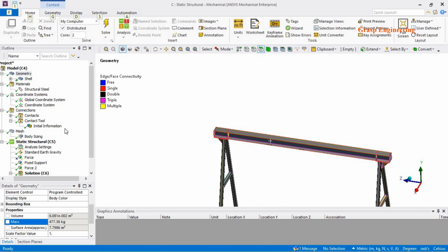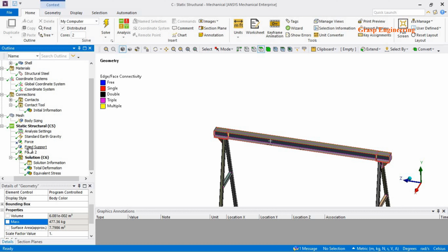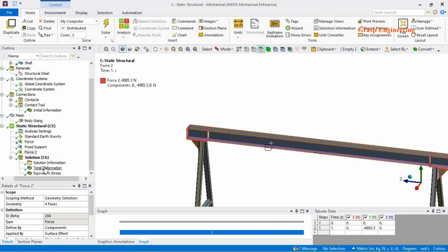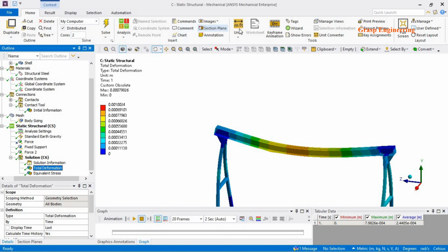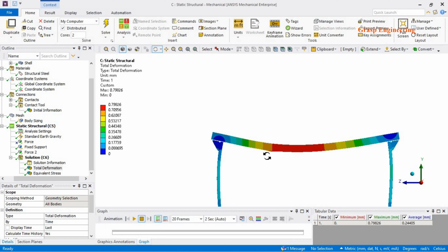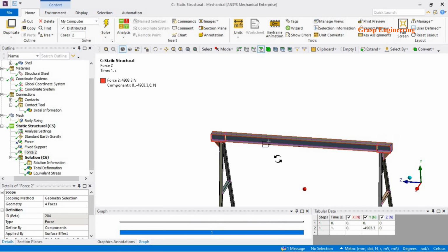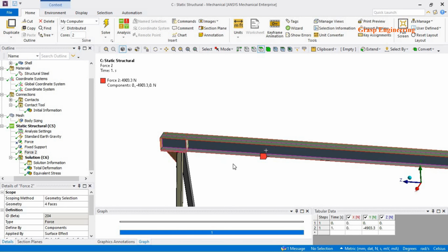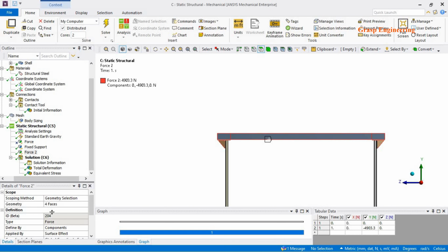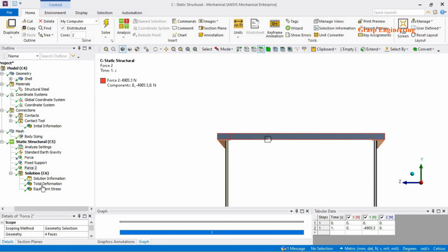Now we can see that the second simulation, where we applied the force at the second position, is also performed. Let's check the deformation. If you see, from 1 mm at the center to 2.79, basically 20% deformation is reduced, so we shifted the positions here instead of the center position. Likewise, you will come to know the importance of the load, which is going to vary across this vertical platform. You need to check the worst case scenario, and accordingly you can perform the simulations.